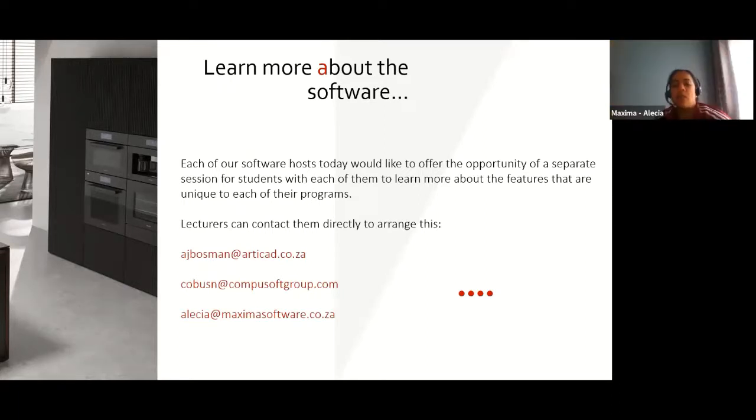Kieran, I'd have to say, while it's not considered illegal to have a distribution board installed within a cupboard, they'd still need to comply with the SANS. I think it's 101, the fundamental requirements. But I suggest the kitchen manufacturer or the installer get something in writing from the client, or actually draft the letter and have the client sign it, saying they have been advised that this shouldn't be done.